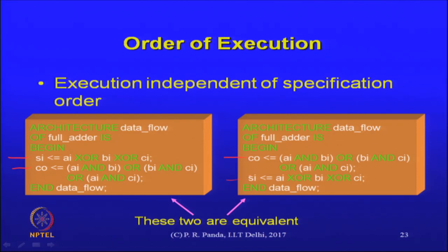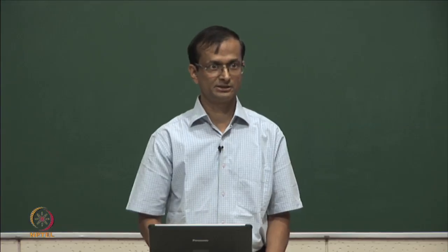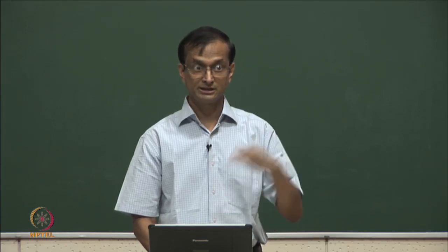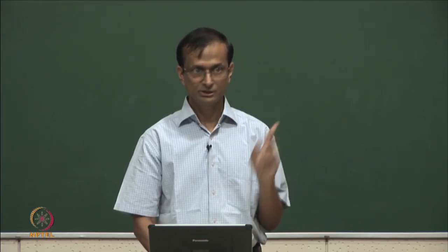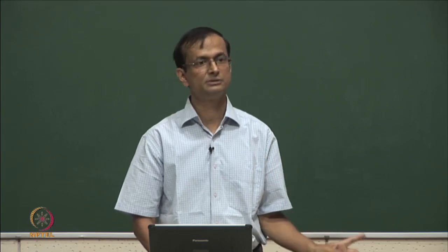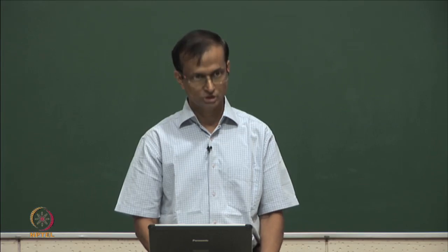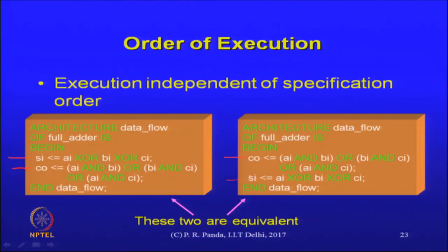If we are writing a sequential algorithm? We will get to how to write sequential algorithms. As of now, this is only a matter of concurrent signal assignment specification. There I do not have the choice. I need some other construct within the language to actually specify a sequential algorithm.